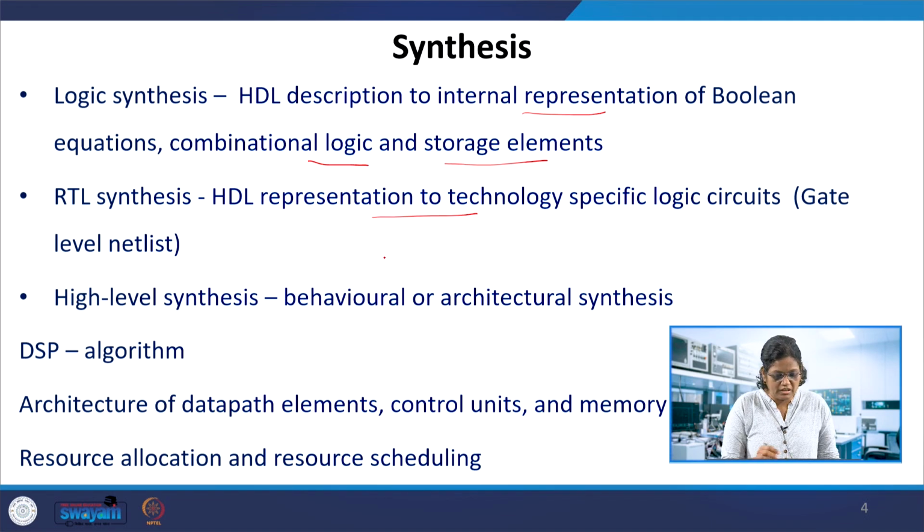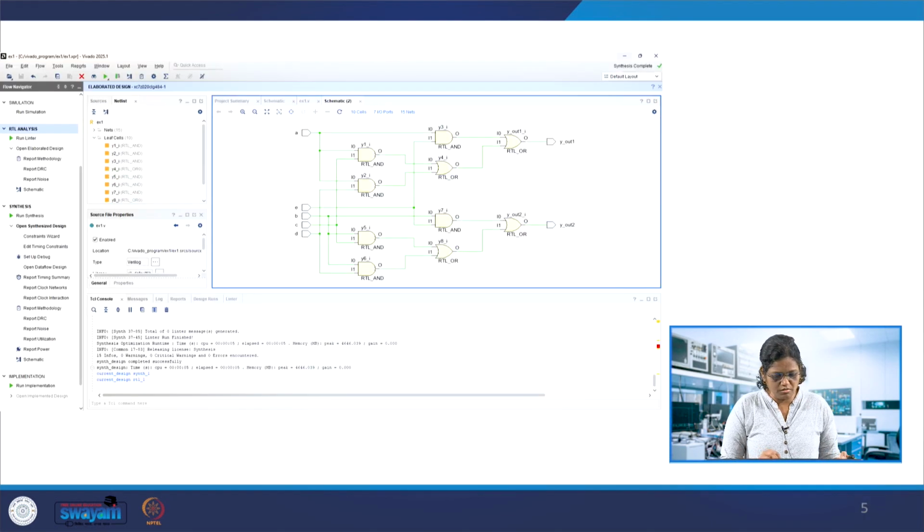So just to distinguish these three listed here, we will be looking at each of them in the coming explanations. When you take the synthesis tool, this is a Vivado environment, you will have this listed over here. After writing the Verilog module, you can get into the flow navigator where you run the simulation.